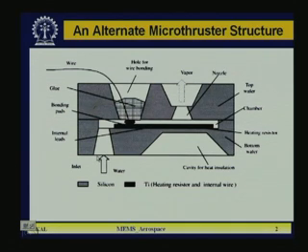In the earlier case you see this is a homogeneous structure, earlier it is one glass and other is silicon, and both inlet and outlet are made in silicon, but here both are silicon pieces, one inlet in the bottom piece and outlet in the top piece. So now in the bottom piece, other than this inlet, they are forming the heater, that is basically the titanium patterned on the surface of the silicon, and then there is a cross sectional view.